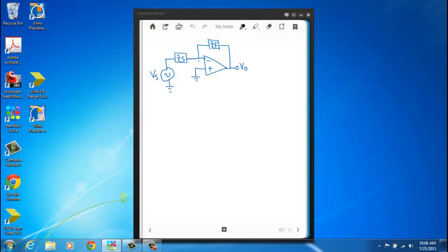And when we write the circuit like this, look what we have. We have an inverting amplifier, right? Because you see how the non-inverting input is grounded, just like when we did the inverting amplifier, our very first op-amp circuit analysis a few videos ago. And you may recall that when we did the node voltage expression and solved for V out over V in, it came out to the ratio of two resistors with a negative sign that indicated the inversion, the 180-degree phase shift between V out and V in.